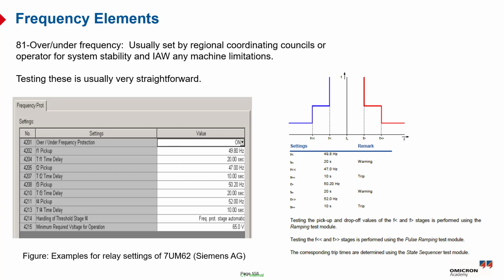So the frequency protection must be coordinated with the automatic load shedding scheme to prevent system collapse or equipment damage during the abnormal conditions. Under frequency can cause higher load currents, overexcitation, and turbine stress, while the over frequency may lead to over voltages, particularly in the hydro turbines.